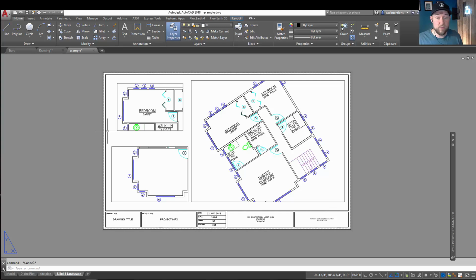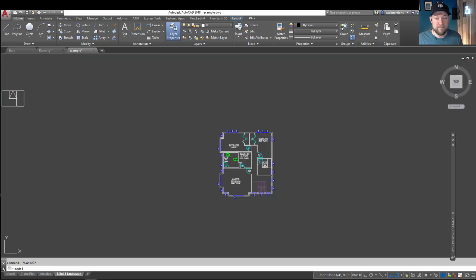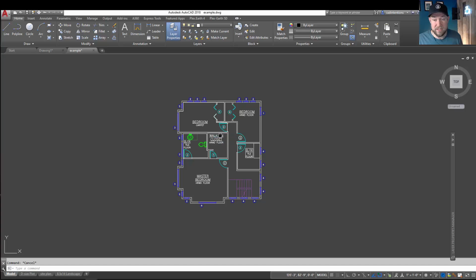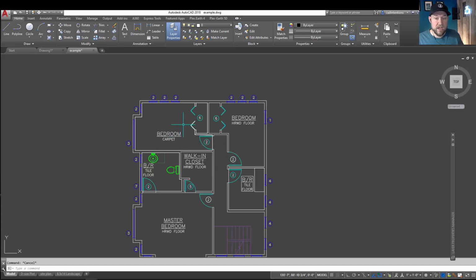Alright, so as I mentioned, I want to show you guys a trick to display your viewport boundary in model space. I've been asked this question multiple times recently, and it's a great way to get a sense of what your viewport is going to show when you create your drawing, and it's going to allow you to create multiple viewports, say along an alignment for a road, for instance. Maybe you would have multiple viewports and you want to show the boundary of each view along your alignment just so you have an idea, or for an index sheet showing the boundary of each drawing.